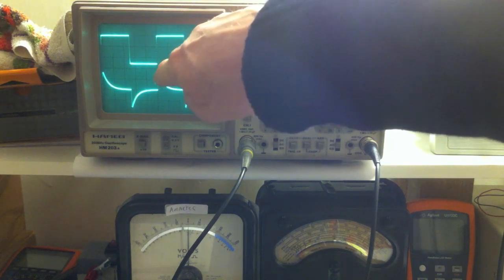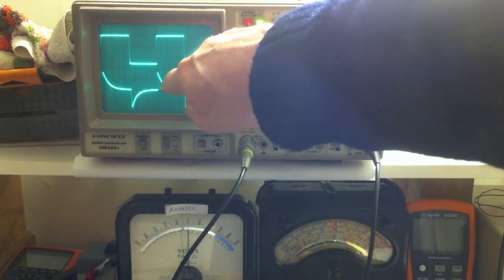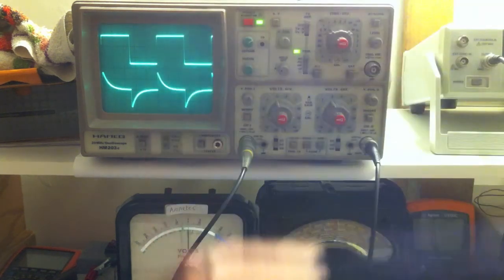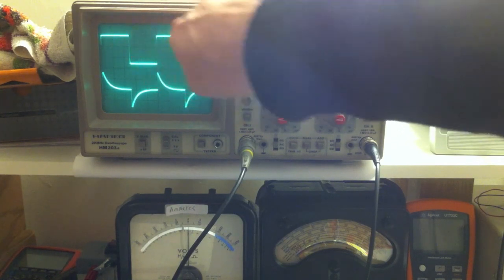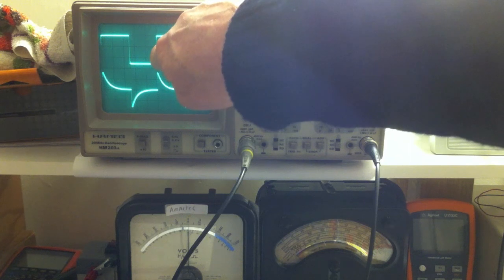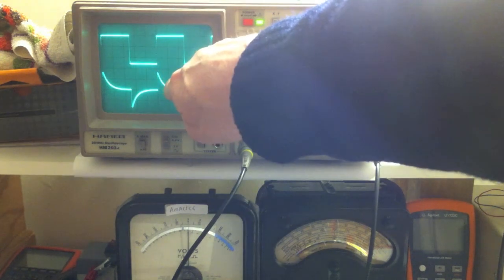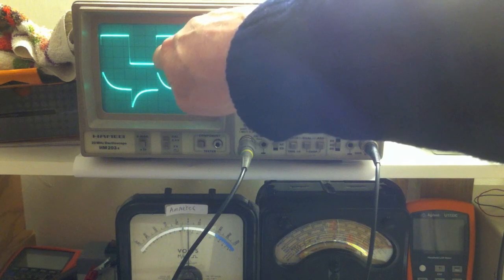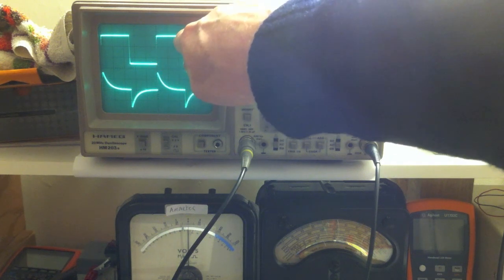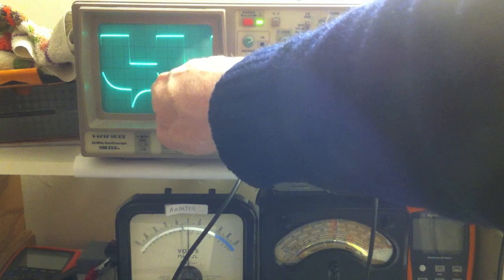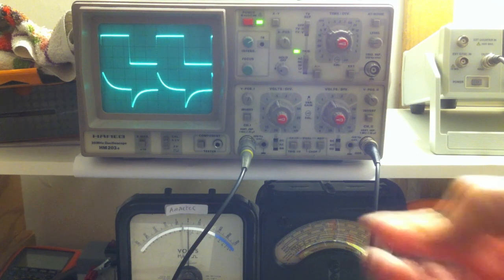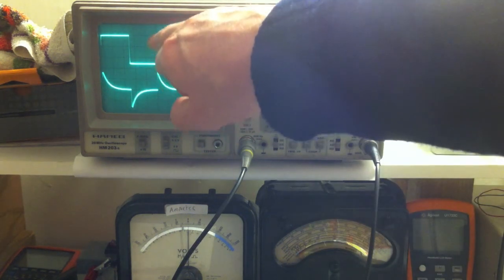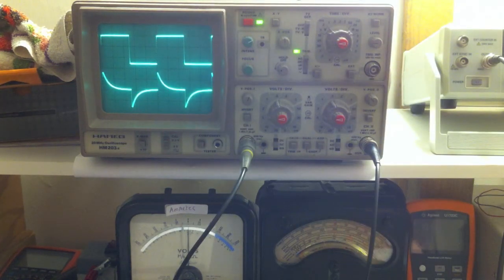I'm showing the voltage across the resistor, but because the capacitor is charging, as I showed in my diagram before, that's going in this direction. Remember, this is V in, not the capacitor voltage. But the capacitor itself is doing this, in exact opposite to that. So obviously, as more of the voltage is dropping across the capacitor, less is dropping across the resistor. That's why you get this differentiator effect. We call it a differentiator because basically it's the gradient of this.